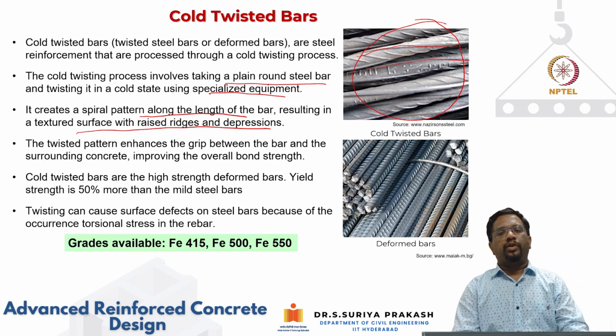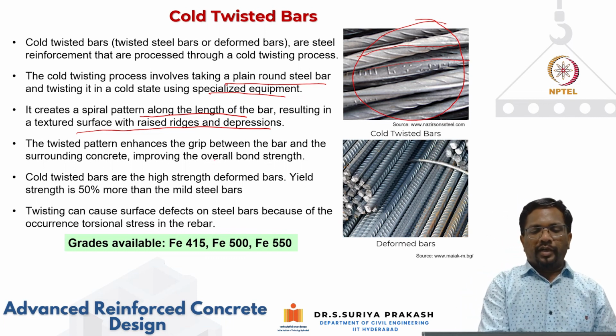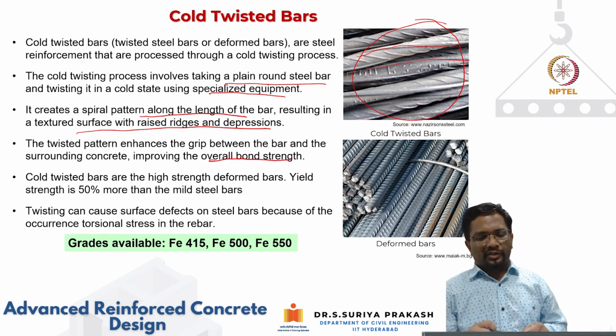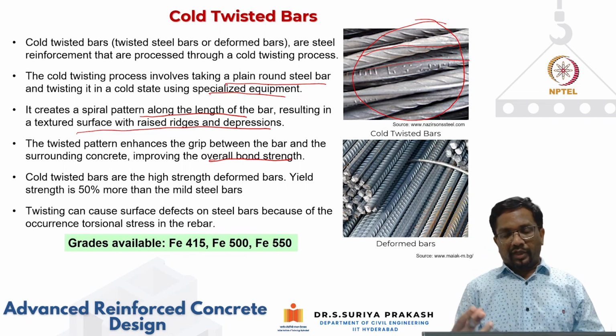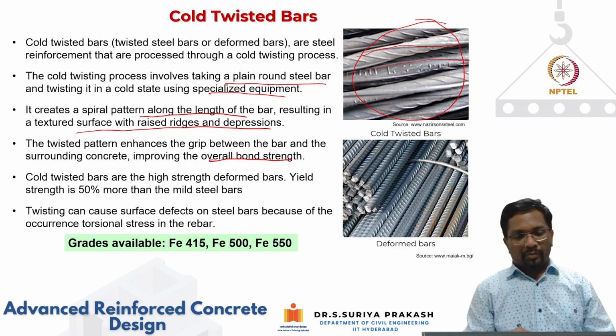This twisted pattern enhances the grip between the bar and the surrounding concrete, thereby helping to improve the bond. But during this twisting process, they also develop a lot of residual stresses. In that process, their corrosion resistance is also somewhat compromised.